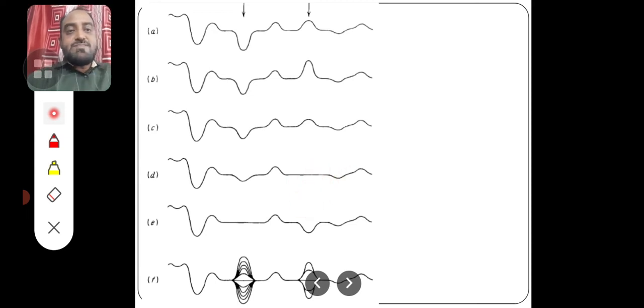Now, what do you understand? Wherever the amplitude in the echo signal is changing at these two locations, you can understand that the target may be approaching or it may be receding. So by just seeing each scan on a raster or a scope, the operator has to very keenly observe and understand where there is a movement, which is a tough task.